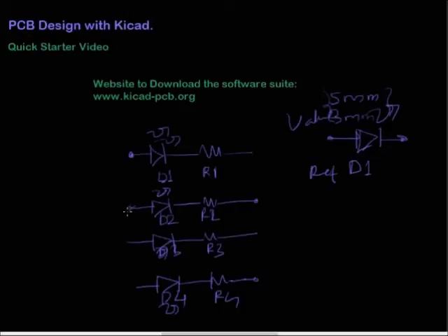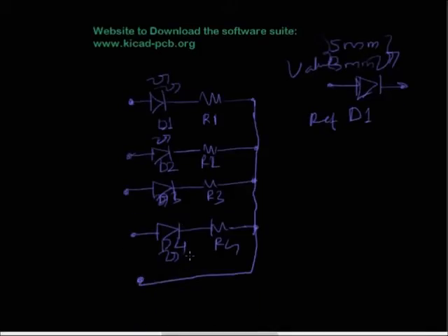So in our small PCB we have four LEDs and 4 resistors. Now since everything should be connected, what we plan to do is these will be driven from microcontroller pins, and hence we have these 4 inputs, and also we need to have a common ground with the microcontroller board or whatever other board that this breakout will be used with. Now, so this is the common ground, and instead of drawing a symbol, I'll just draw it as a pin on the board.